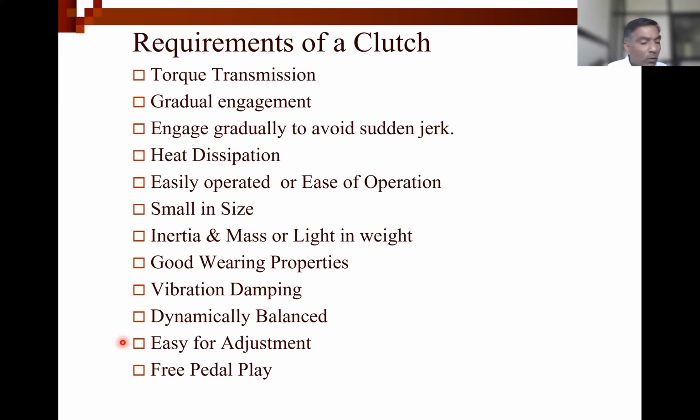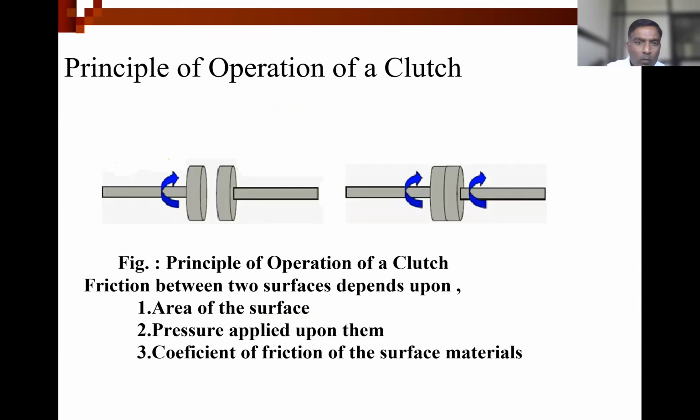There will be disengagement of the clutch, or sometimes slight friction. So sliding is going to take place between the flywheel and the friction plate or clutch plate, and that will wear the clutch plate. Okay.